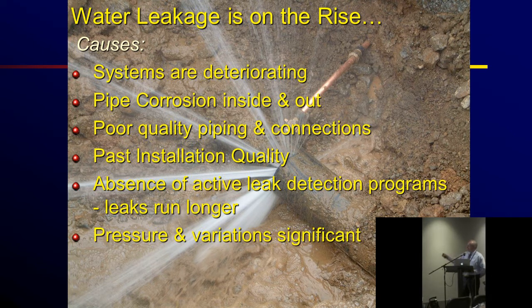And inasmuch as a lot of this is relevant to metal pipe, we still have many of the same issues with plastic pipe. Worldwide, there's more plastic, elastic, polyethylene pipe going in the ground, which presents, from a leakage control perspective, more challenges because it doesn't transmit leak noise very far. Some would argue it doesn't go very far at all. Not predictably well. You might get lucky and be able to acoustically find leaks on plastic or elastic pipe, but not with certainty and not every time.